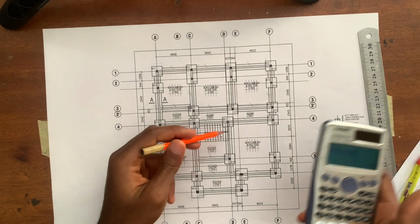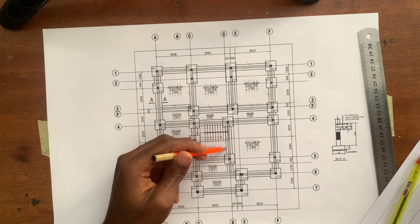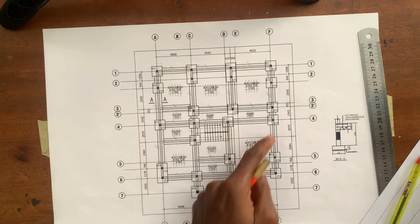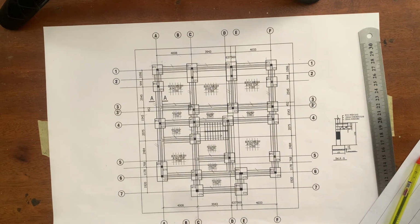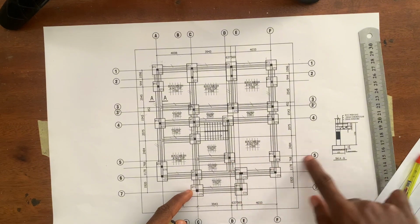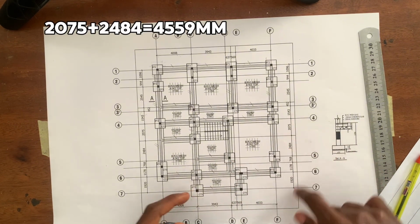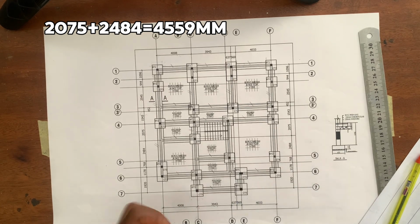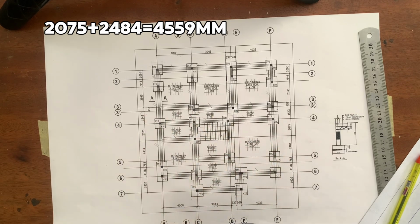The next one we're going to be measuring is this trench here. You see that this trench here and this trench here are similar, so we're going to be doing them together. From this call out here, call out 4 down to call out 5, we need to determine the dimension. We have to add these two dimensions together: 2075, which is from here to here, plus from here to here, which is 2484, will give me 4559.